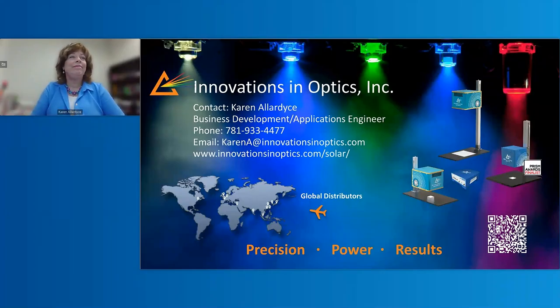Next question. Is there a trade-off between uniformity and spectral accuracy when adjusting LED intensities? Well, not in imaging systems like the LumiSuns, because the uniformity is determined by the imaging optics, not by the LED intensity ratios, but that is something to look for in other systems. So the imaging systems enable true wavelength tunability without compromising accuracy. I think that answers that one.